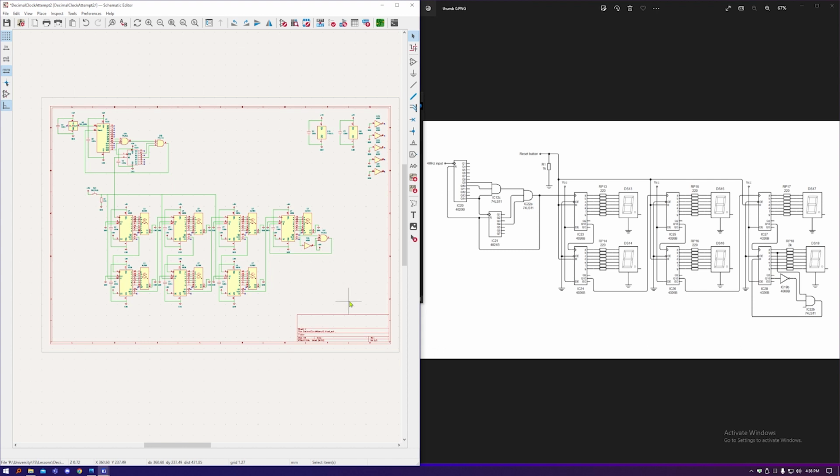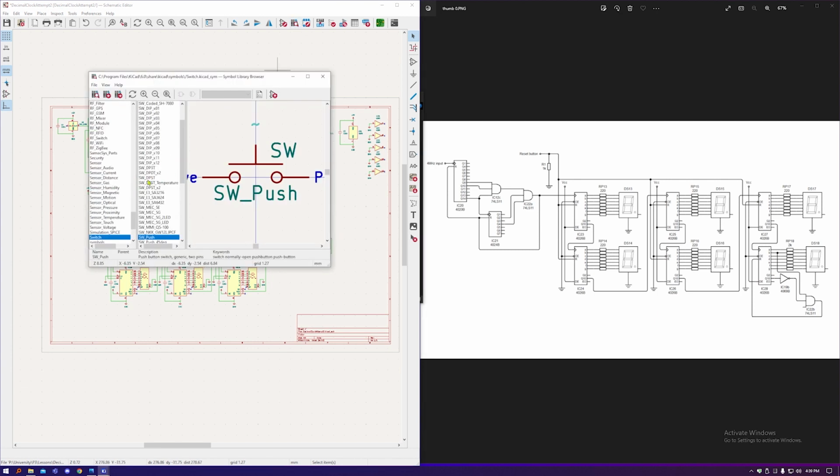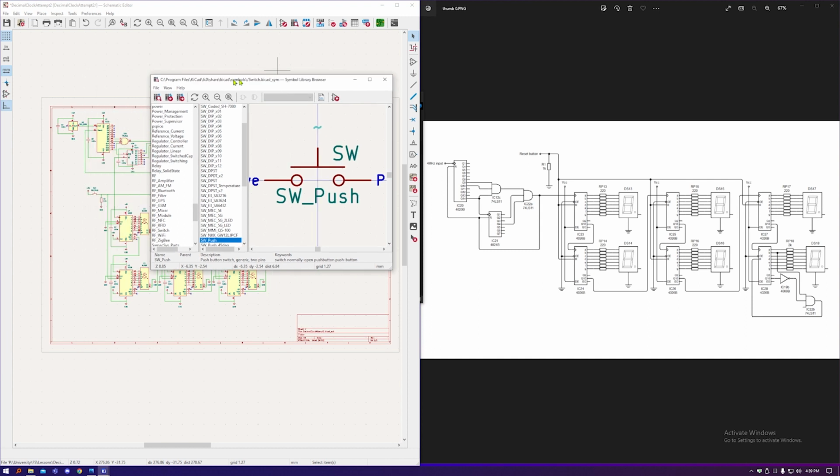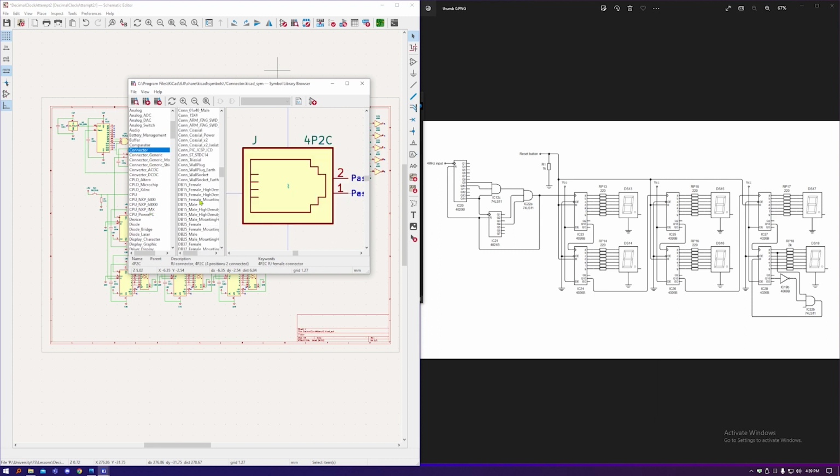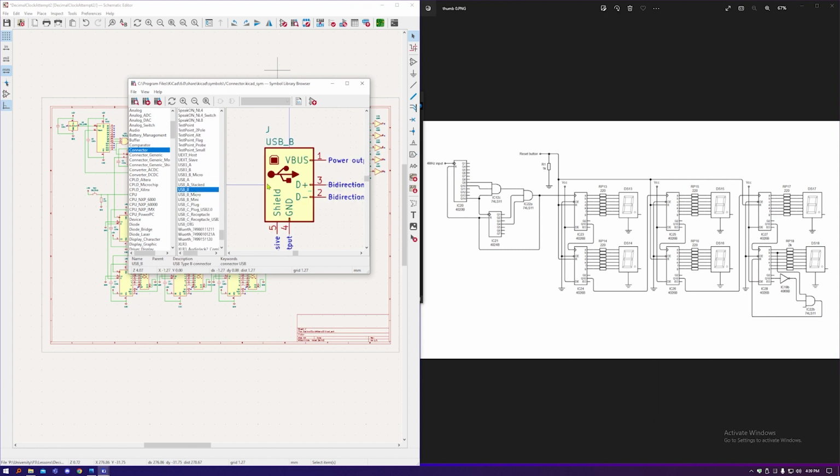Hello, Fred from the future here. Just realised that I forgot to add in the power connector, so I'm going to quickly do that now. The board runs on 5 volts, so I'm going to just use a USB connector. My favourite is type B, the sort of square one, because I've got quite a few of those connectors and leads, and they're very mechanically robust, unlike newer versions like USB-C. So if I scroll down in the connector section, we should have USB-B, there we go.